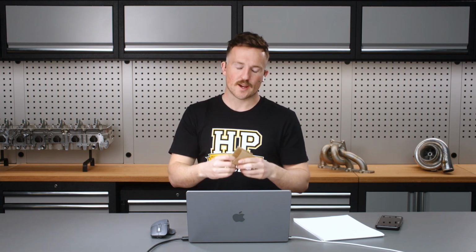Other things to consider are whether we will actually be able to make the bends at all. So with this piece of cardboard, imagine if we were trying to make a part like that with a U shape, but pretty long flanges quite close together. Sometimes we would bend that one up, and then we go to put it in our sheet metal folder here and bend again, but we find that this edge hits the parts of the folder.